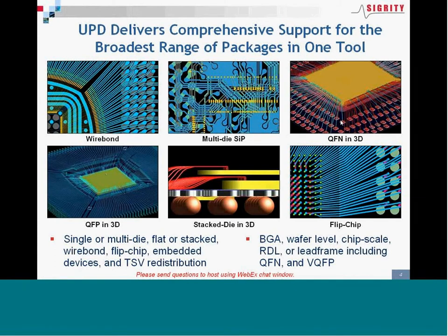Now, one important point I want to emphasize is that companies that rely on outsourced design and assembly services often find themselves dealing with multiple versions of the same design, since these manufacturers are reluctant to share design databases with competing foundries. Using UPD, a company can lay out the design once and send the same database to all its suppliers, ensuring consistent package performance regardless of the manufacturing source.